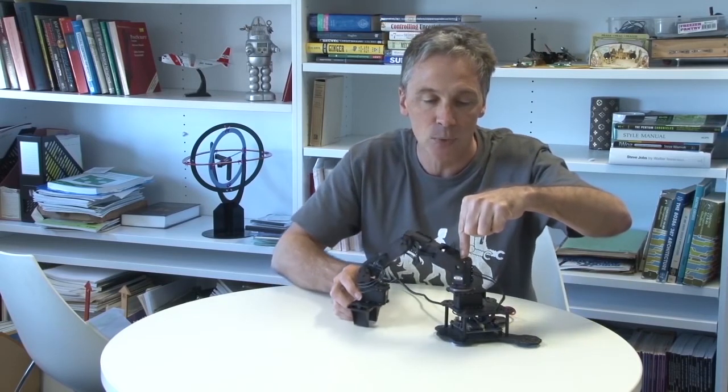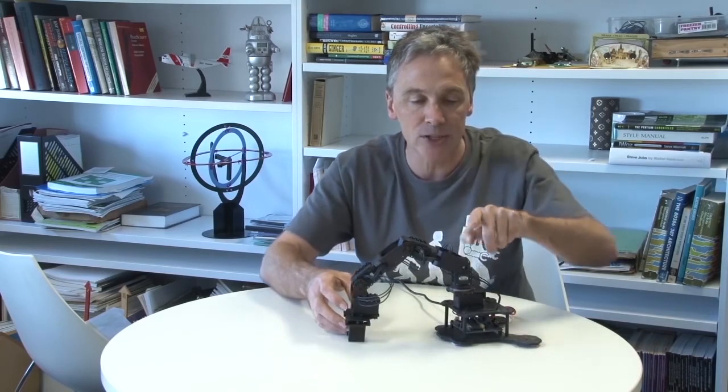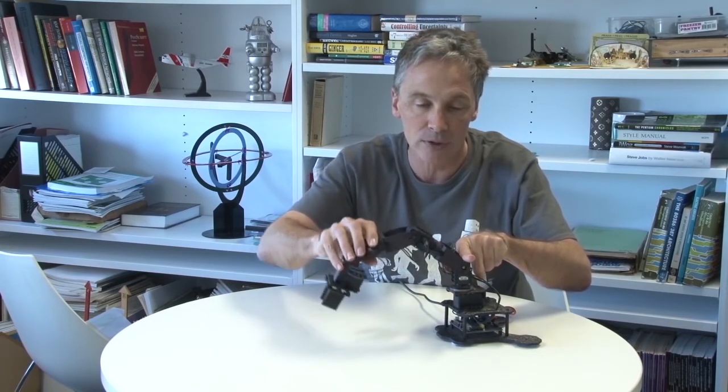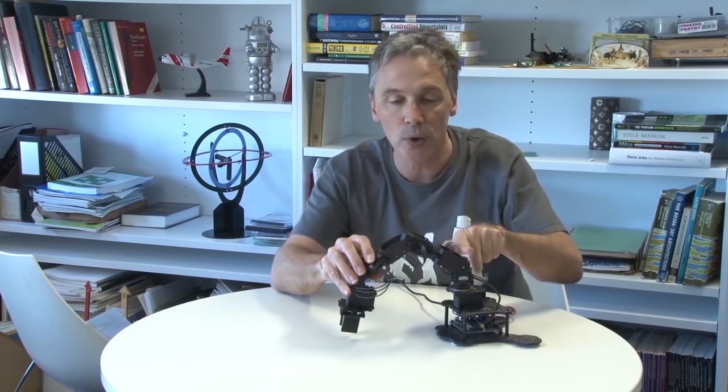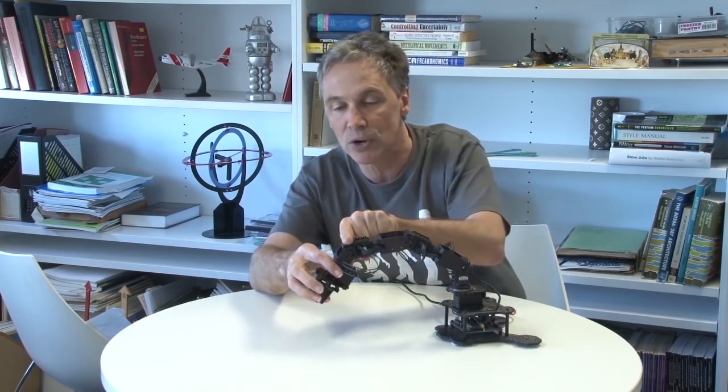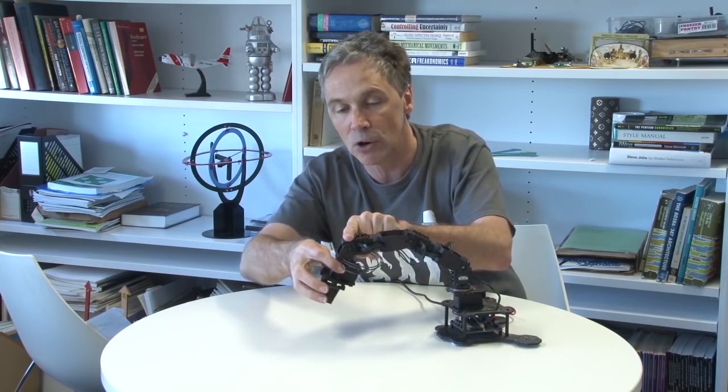This small robot has got 4 degrees of freedom, 4 rotational joints. So the first rotation is around an axis like this. We see that the whole arm rotates around the base. The second rotating joint has got an axis like this, and we can see that the whole arm can rotate around this axis here. The third joint is a rotation around this axis. We can see that the lower arm rotates around that. And the fourth joint is a rotation around an axis here. We see that the whole gripper mechanism rotates with respect to the lower arm.